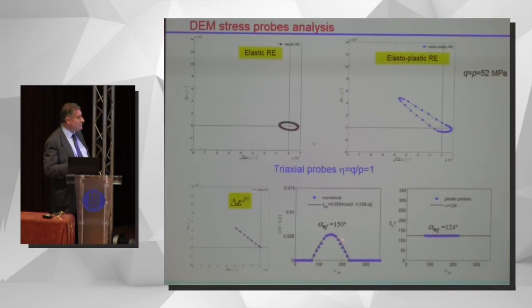If you look at the magnitude, it just follows the expected cosine, so things work beautifully, and that's what had already been observed in previous works. And here we have that the normal to the yield surface is 150 degrees. So it's not associated, not very far, but it's a non-associated plasticity. So in this respect, it points to a very simple model, at least at this level.